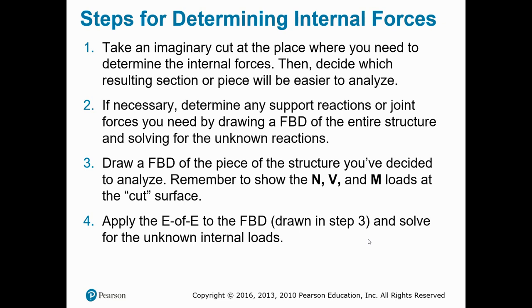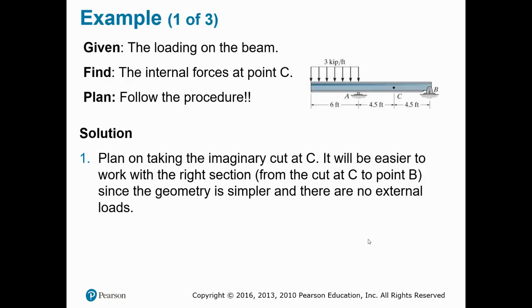After we have done the free body diagram and written our equations solving for the unknowns for the entire structure, we move on to step 3, where you do your imaginary cut. When you do your imaginary cut, we add the normal force, shear force, and the bending moment to that cut. And then step 4, after you do your cut, we do the free body diagram and solve for the unknown internal loads.